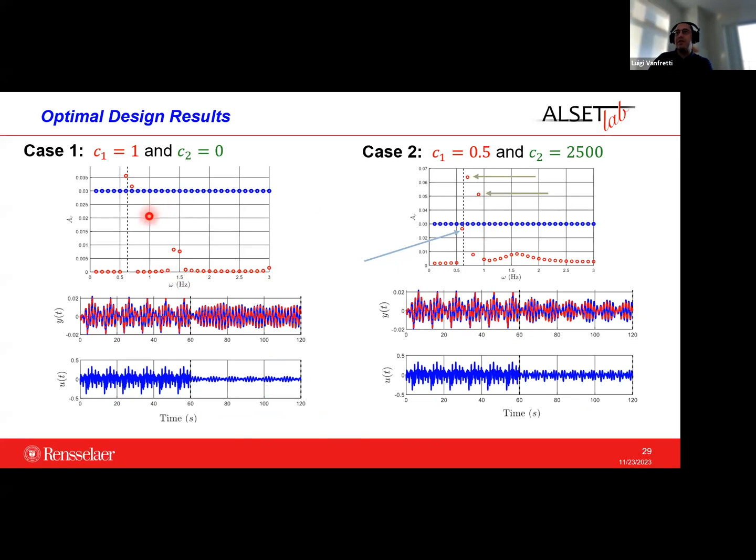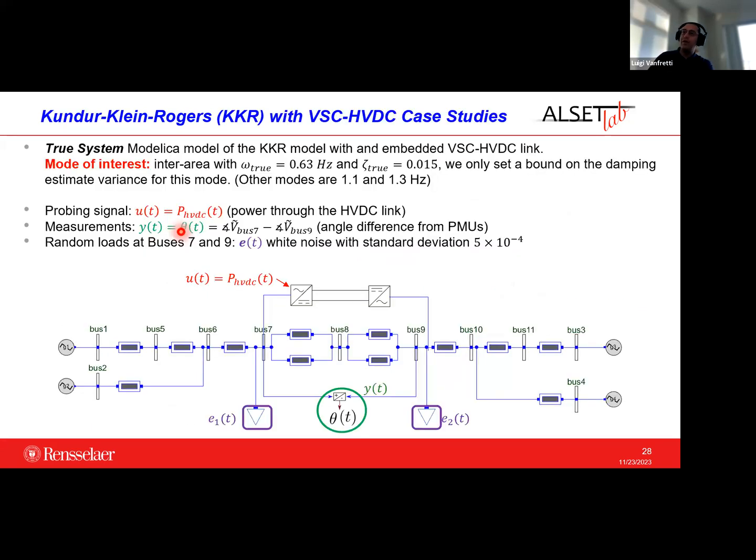So effectively, you can see the main dynamic of the inter-area mode is right here with the dashed line. And you have a couple of frequency injections here, but you also have some there. This is another area, the local dynamics of the other machine. So there is a local dynamic that is going in like this between G1 and G2, another one that goes like this, and then the inter-area dynamic is these guys against these guys like that.